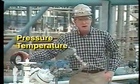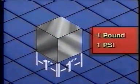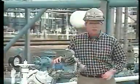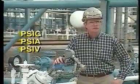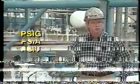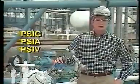We'll look at pressure and how it's measured first. As you learned earlier, pressure is a force per unit area. The force is usually represented in pounds, and the area is given in square inches. The unit is abbreviated PSI. In addition to PSI, you'll see that other units are used that relate to specific conditions of pressure. Other units that measure pressure are PSIG, pounds per square inch gauge, PSIA, pounds per square inch absolute, PSIV, pounds per square inch vacuum. We'll discuss their use as we continue through this section.